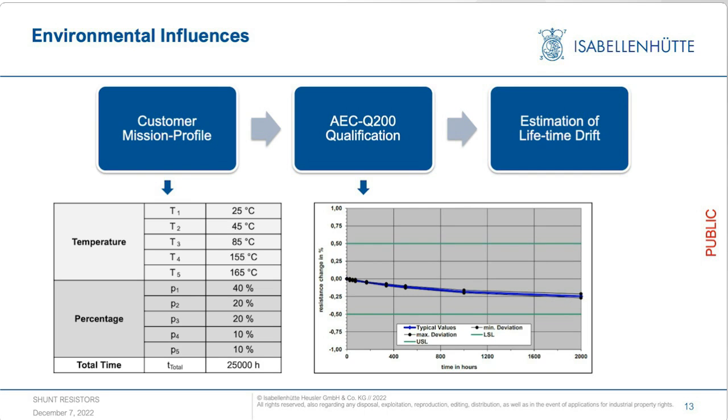We then take the qualification results of the AEC-Q200 environmental testing definitions, and with a statistical model we can estimate the lifetime drift of that shunt.